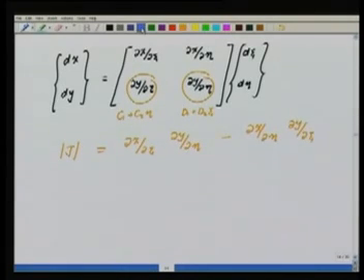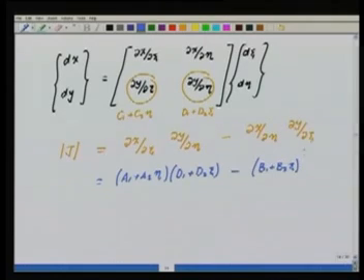By what we have done, del x del ξ is a1 plus a2 η. This one, del y del η, is d1 plus d2 ξ, where d1, d2 are again obtained from the previous expression. Del x del η is b1 plus b2 ξ, and del y del ξ is c1 plus c2 η. So you see, in the product, what do I get?